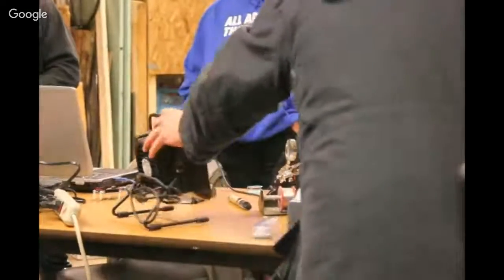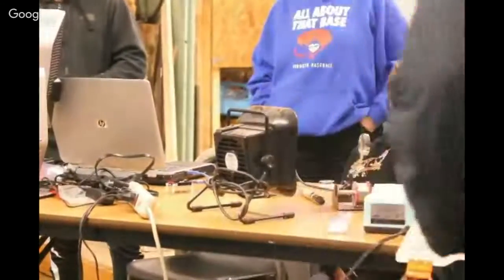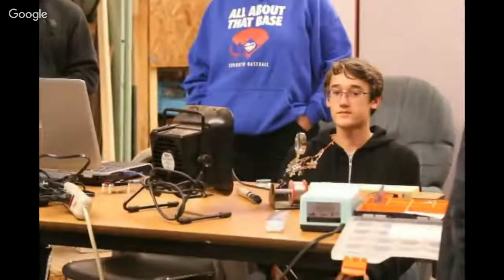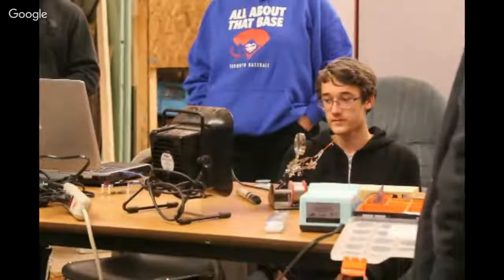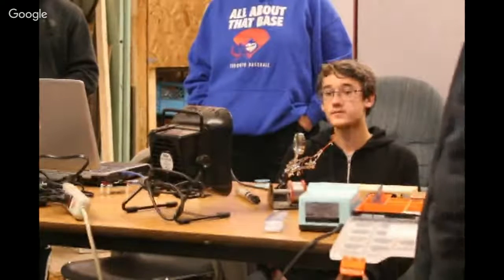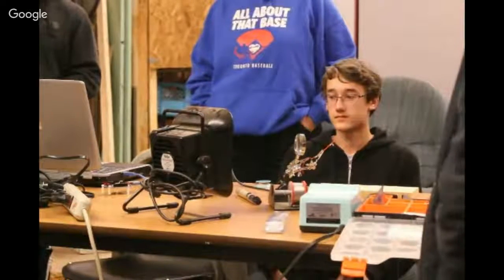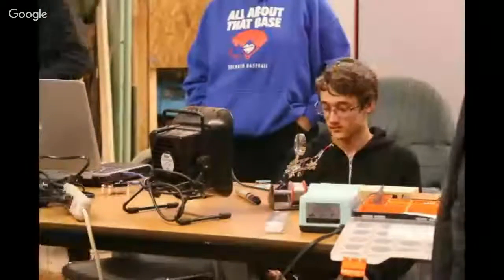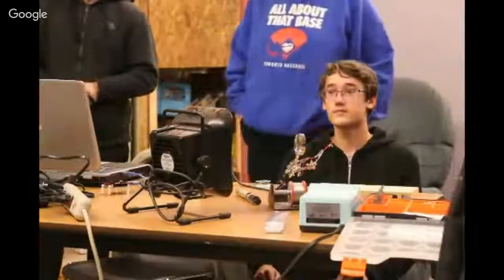If you're soldering and desoldering boards that are certified for use in the European Union, they're all done with non-lead solders, and what this means is you're going to have to get to a bit higher temperatures to pull the components off. And it's kind of a pain to get good results. I really prefer a leaded solder for hand work, but just be aware that if you're working on a board and wondering why your normal iron settings aren't getting a chip off, it's probably because the non-lead solders are higher temperature solders.